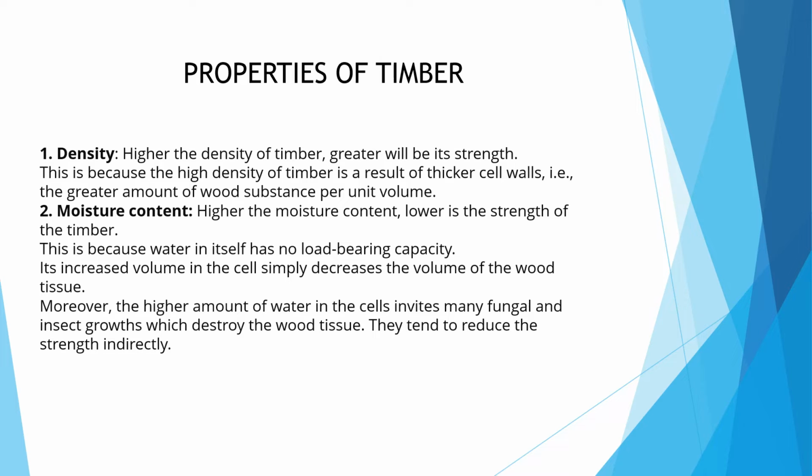Next, properties of timber. First of all, density. The higher the density of timber, the greater will be its strength. This is because the high density of timber is a result of thicker cell walls, the greater amount of wood substance per unit volume. Moisture content. The higher the moisture content, the lower is the strength of the timber.